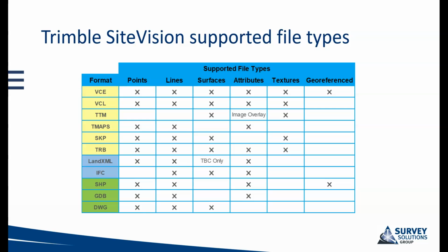We can also create an image overlay. So in TBC we can export an image, for example of a cut fill, as a PNG, and with our supporting georeferencing information in PGW file format, this can then be used in SiteVision to drape the image over the model.